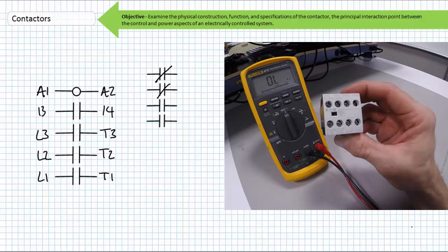This example auxiliary contact block contains 4 additional switches, 2 normally closed and 2 normally open. This is the second set of auxiliary contacts associated with this contactor, so the first digit of this terminal is given the number 2. Since it is a normally closed switch, it is assigned 1 and 2 for the second digit, for terminal numbers of 21 and 22.